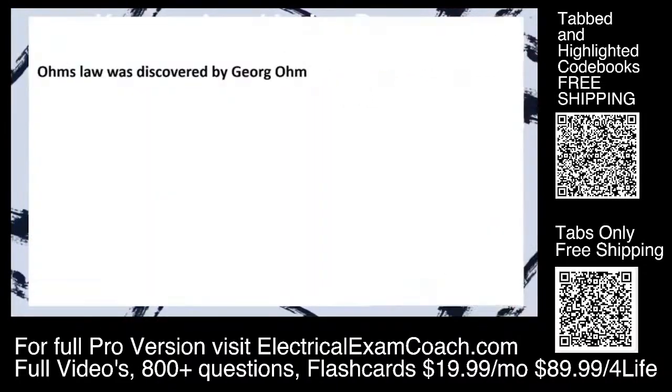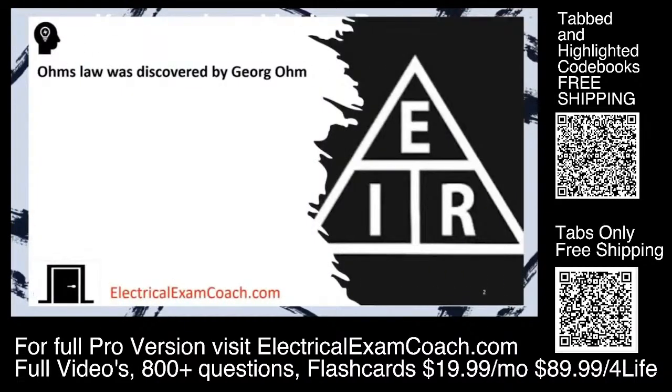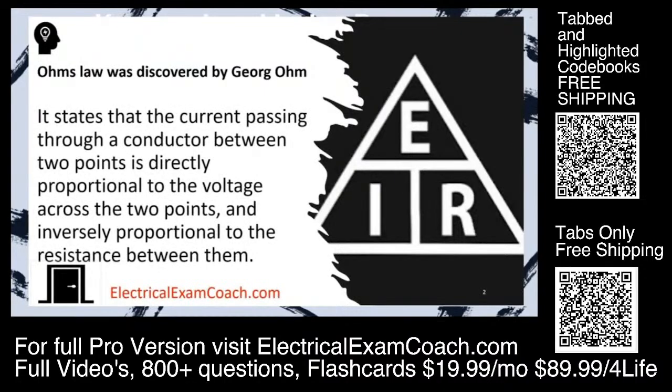Let's get to it. Ohm's Law was discovered by Georg Ohm, and the relationship states that the current passing through a conductor between 2 points is directly proportional to the voltage across those 2 points, and inversely proportional to the resistance between them. Now that sounds like a mouthful, but we're going to break it down piece by piece and see how it's relevant and fundamental to getting our license or certification.